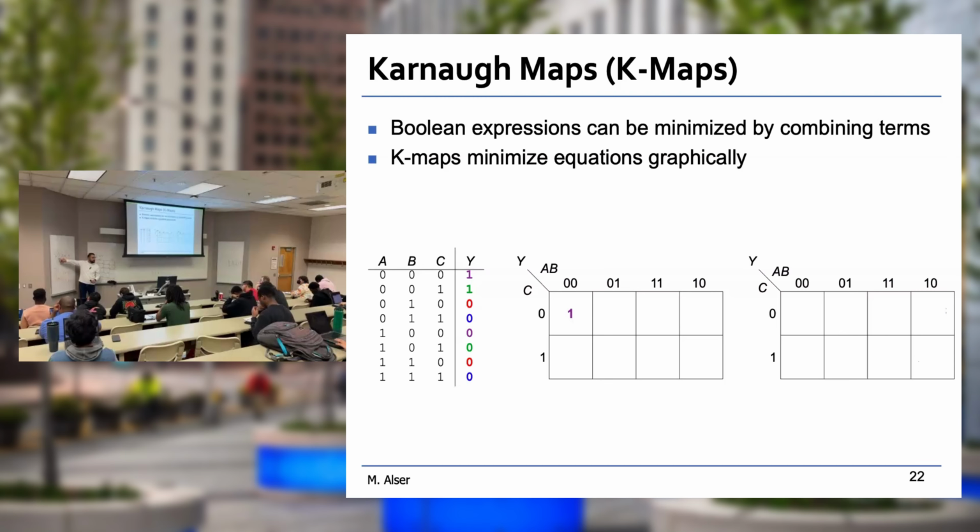But remember this, when you build this equation and you see it vertical, then it means the equation does not really depend on that variable. And this is true. You can see it here. If the variable is 0 or 1, the output is still 1. It means we don't care about the third variable. So just remove it from the equation. Don't add it from the beginning. And that will be the most simplified equation. Now, if you look at the equation, oh, it looks like A bar B bar plus A bar B bar, then it's directly A bar B bar. This is your equation. And you will see this next time. When you look at this vertical bar, just look at those two variables, and that's it. That will be your equation. Don't try to add two terms together. Yes, please.